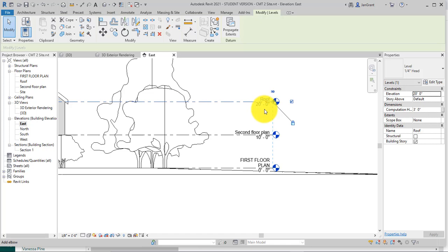We really should have uppercase for all of these so that when we drag them onto our sheet, this will be the name of the drawing. So we can either click on this heading and click again and replace it with second floor plan. Click in space.